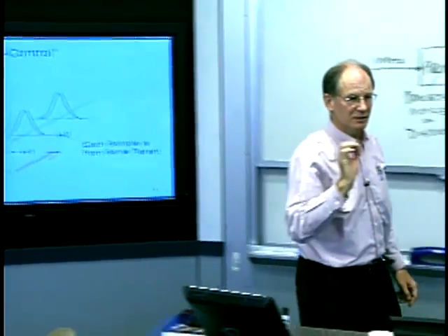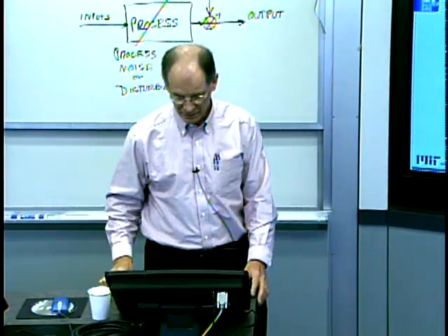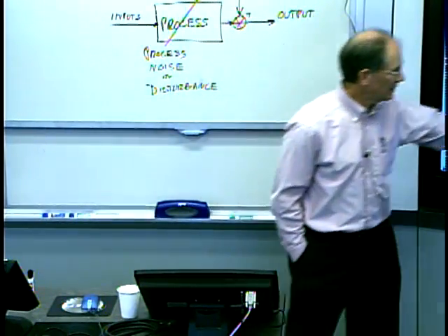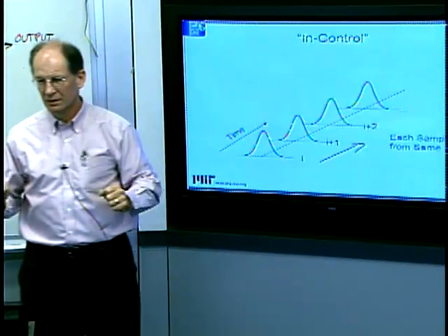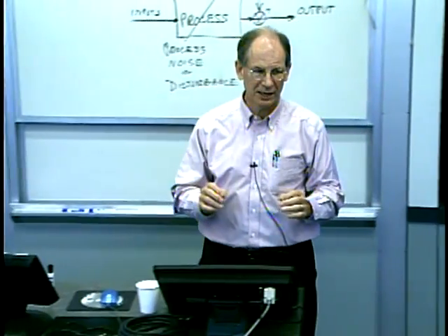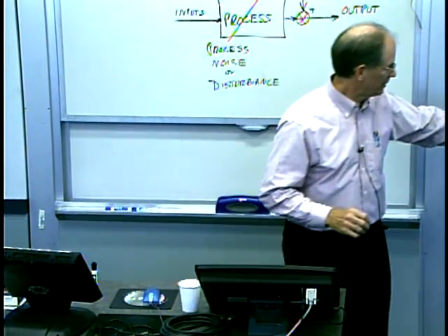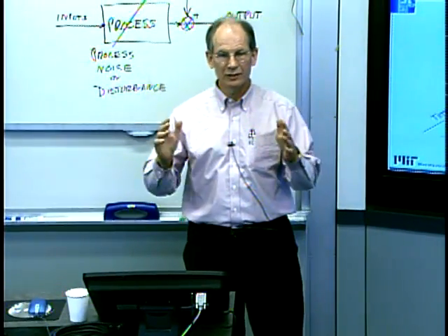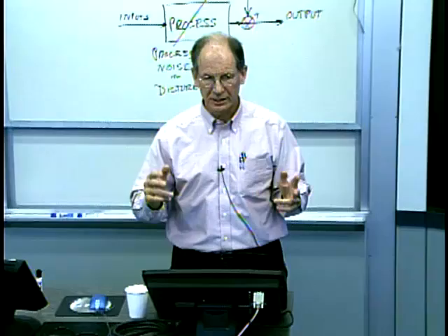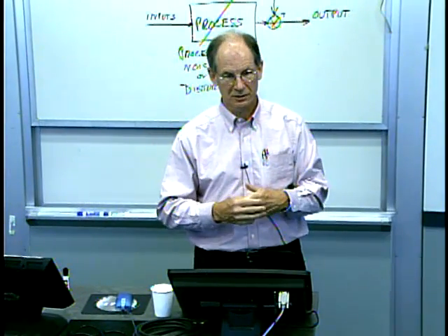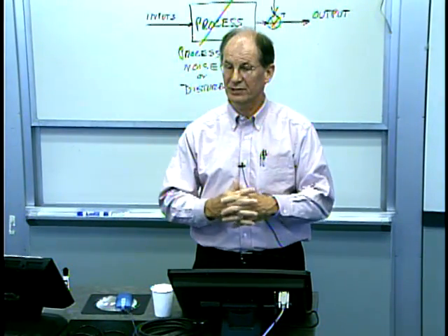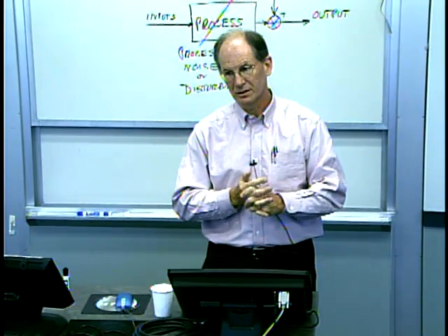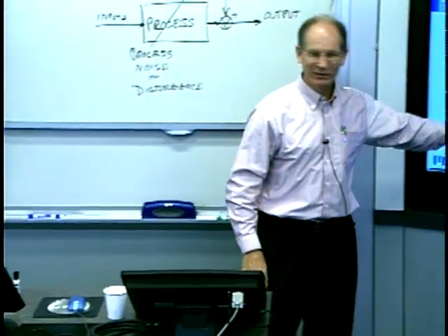Okay? This is the concept of a state of statistical control. The underlying parent distribution, the true random behavior of the process, is following this curve and never changes. If you've achieved that, then by the Shewhart hypothesis, you're in a state of statistical control. And that's essentially the best you can do. The best you can do. And so your process will never get any better than that.